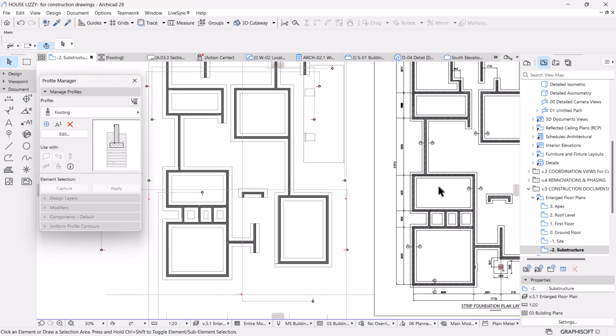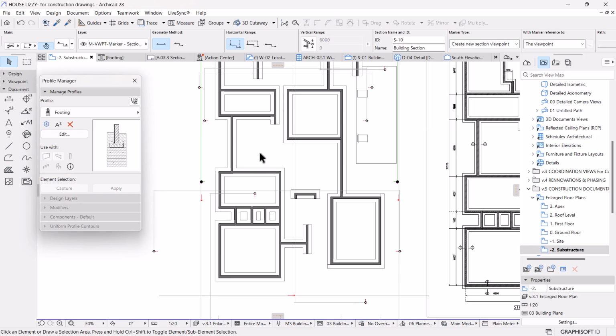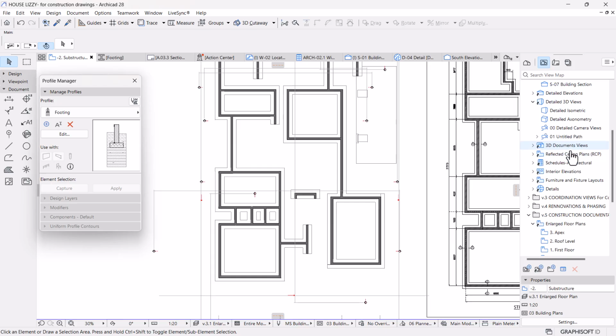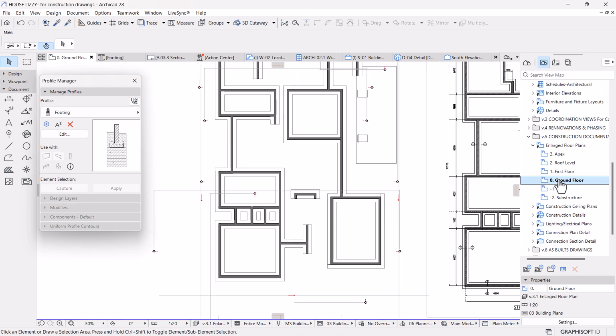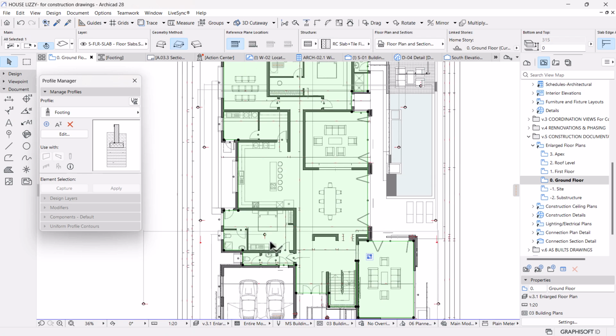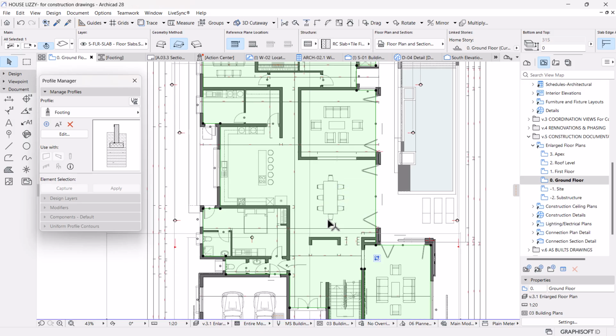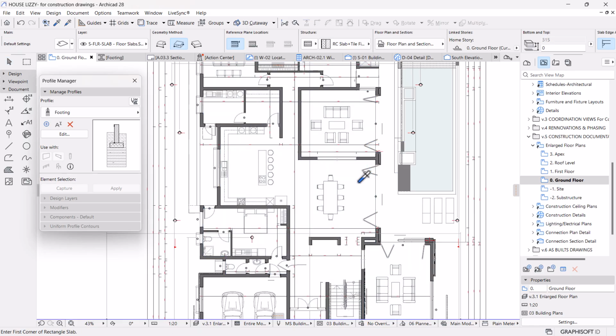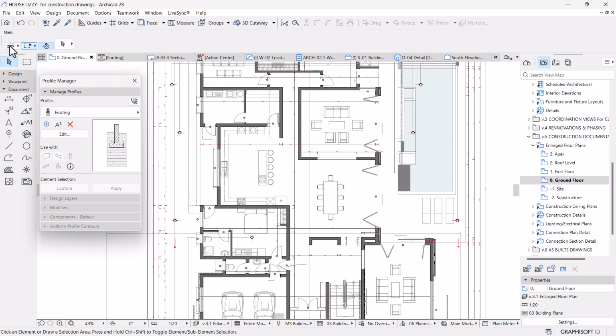So let me apply a slab there. I'm gonna go up to the ground. We're not going to have this kind of floor or slab that is applied on the footprint of the building. We're going to do it portion by portion, to represent this material. We want to get it accurate. So I'm gonna pick the parameters of this, then I can delete that, hit W to provide this.